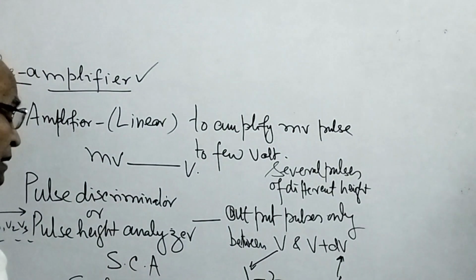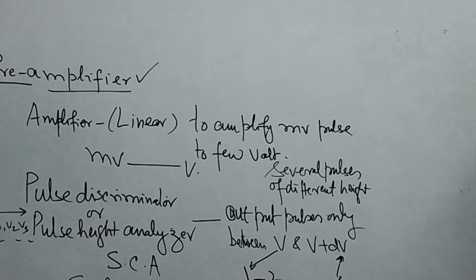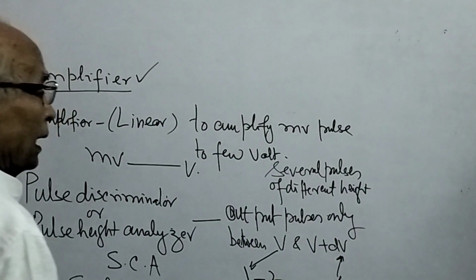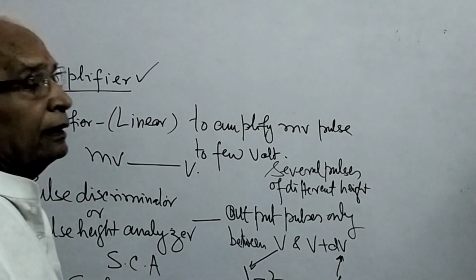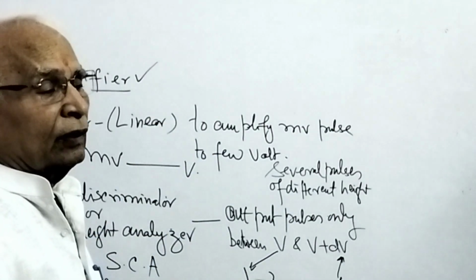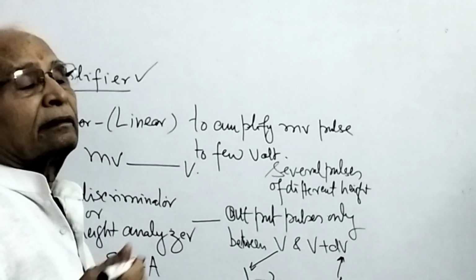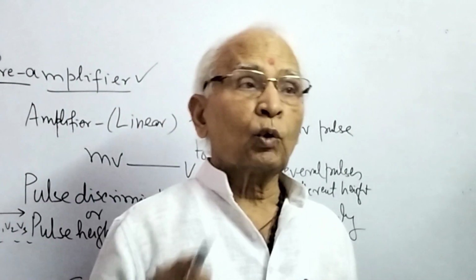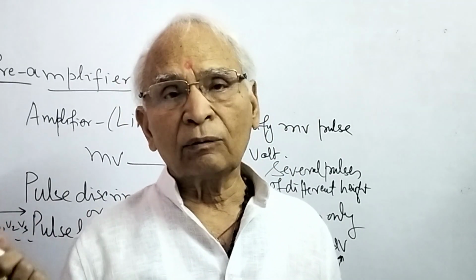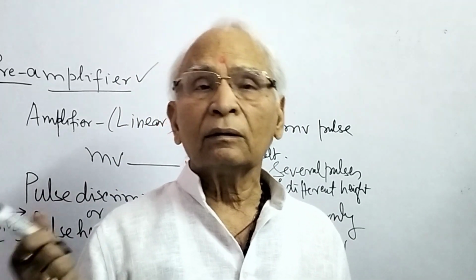So these scalers are electronic circuits which are used in the laboratories for counting pulses. Electrical pulses are counted one by one. Earlier we had binary; now we have digital decade scalers based on 10. A scaler based on 10 means when 10 pulses come, we get 1 pulse at the next stage. Earlier it was binary, 2 to the power n. So we had a 256 counter, 512 counter, 1024 counter, like that.